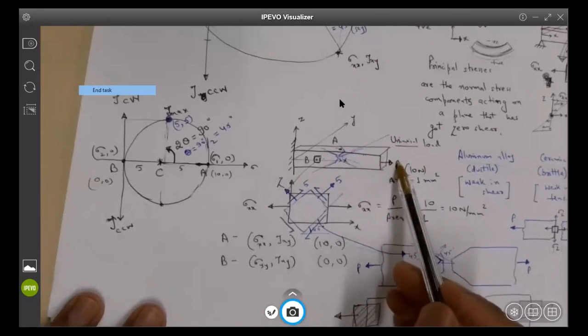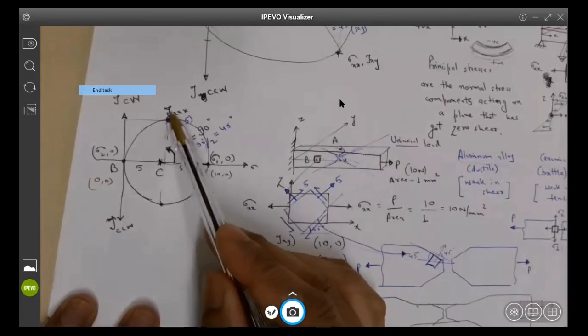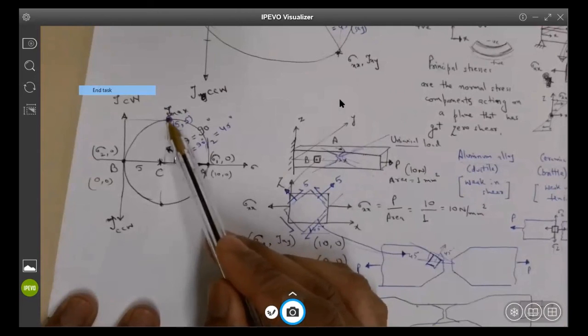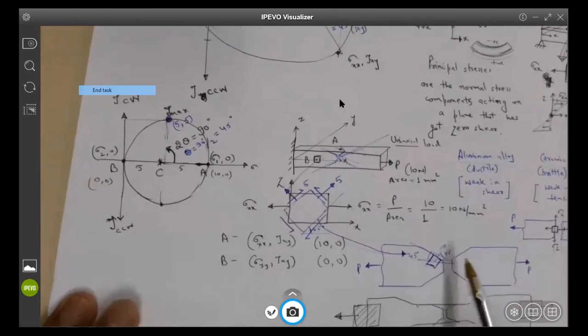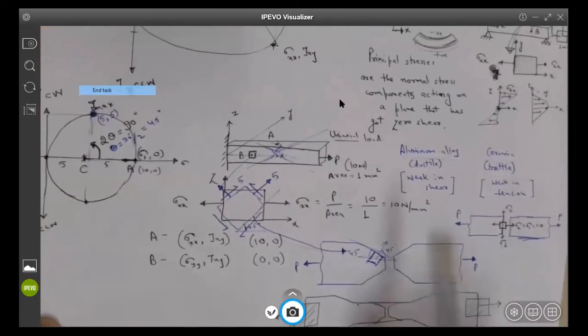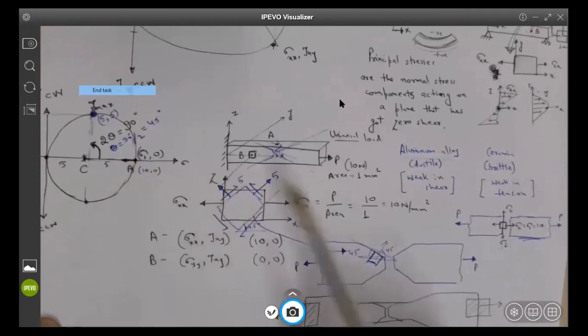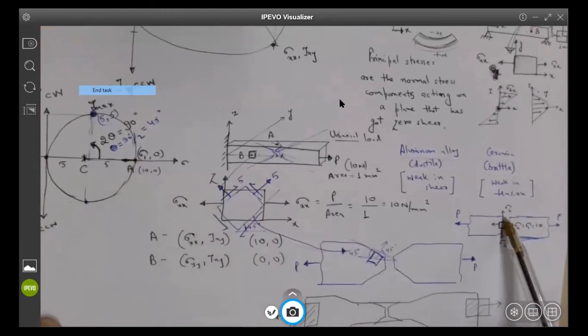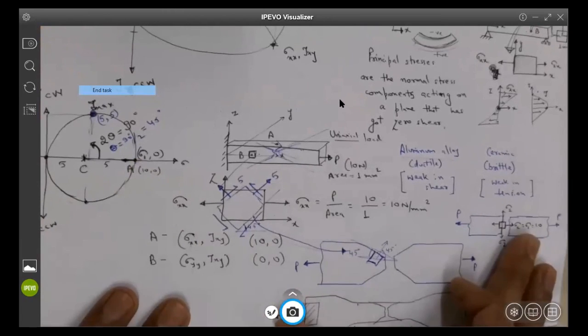So we are applying a uniaxial load, and we saw that if the material is ductile, I'm concerned about the maximum shear stress that happens at 45-degree planes. I actually found in experiments that this is how the necking happens. But if the material is brittle, then I'm worried about these points, the max principal stress points. And that basically tells me how the failure will take place. So these are basically the discussion with the uniaxial load cases.